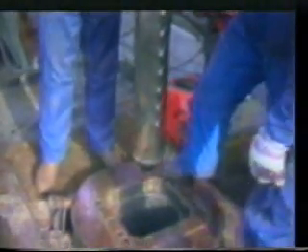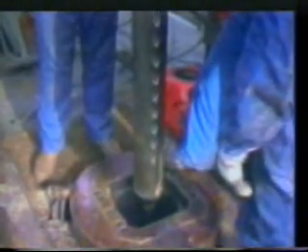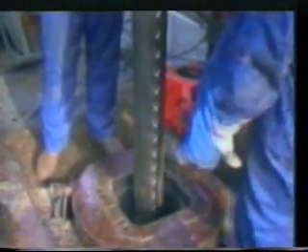If through tubing perforating is part of the completion plan, the perforating gun is lowered through the tubing or on the end of the tubing and fired after the well's surface flow control equipment is connected to allow the formation fluid to rush into the well and clean out the perforations.